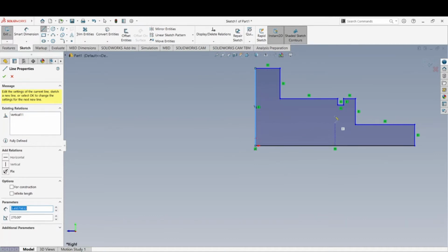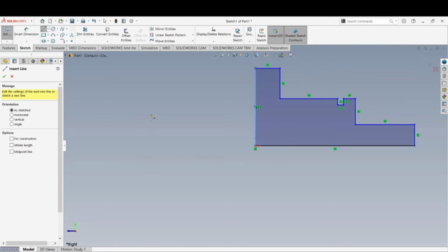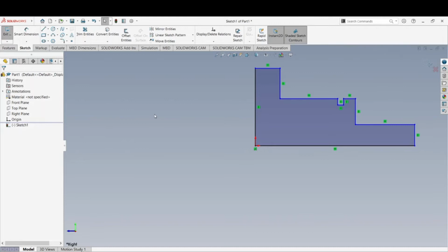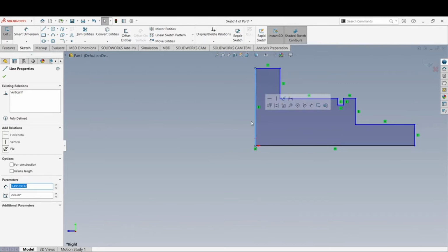This area has to be this shaded color. Reason being, if it doesn't, it could more than likely be an open box. It's not completely chained all the way around. And I'll demonstrate that by erasing. I'm going to push the escape key so I get out of my line sketch mode. I'm going to take this line and delete it.